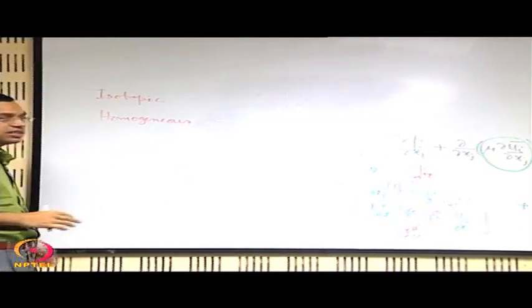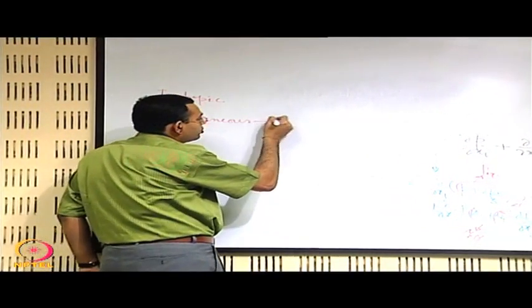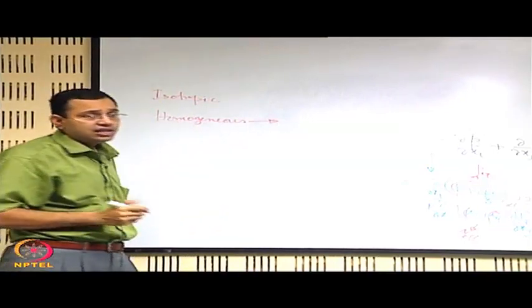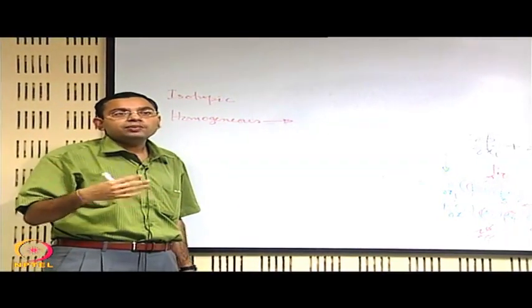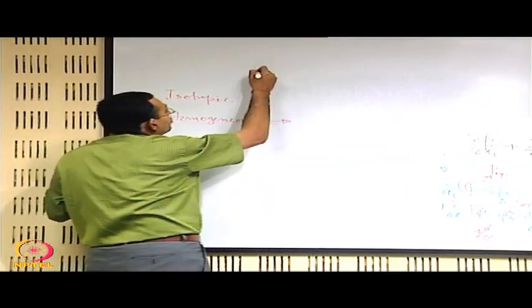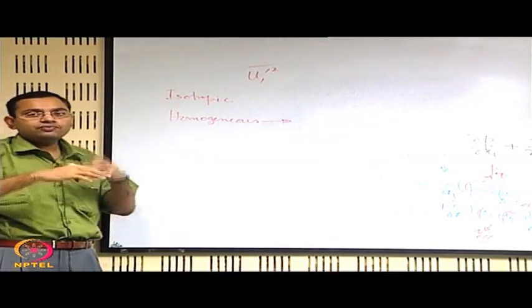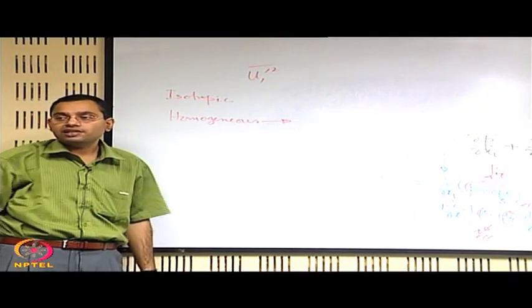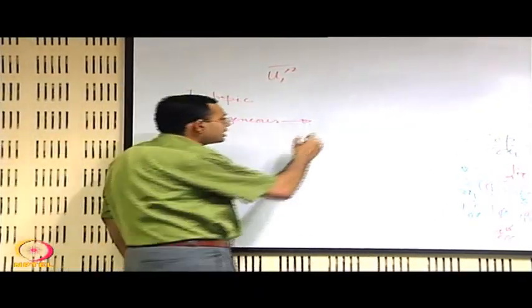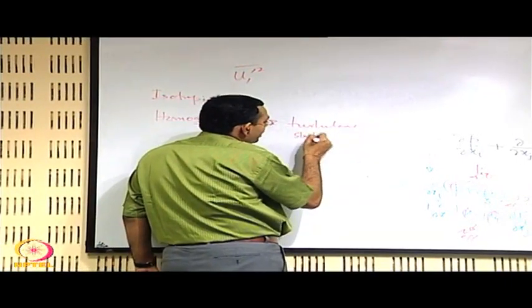this terminology at least we introduced in the previous lecture, and what we remarked is that if you have a homogeneous turbulence, it means that the turbulence statistics are independent of position. So that means if you have say u1 prime square at a point, then if you go to different points you will get the same turbulence statistics. That means turbulence statistics are invariant under translation.